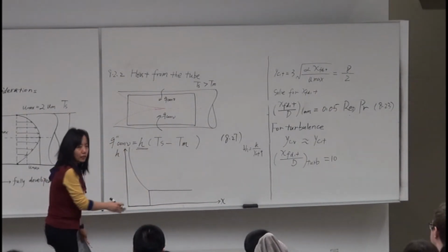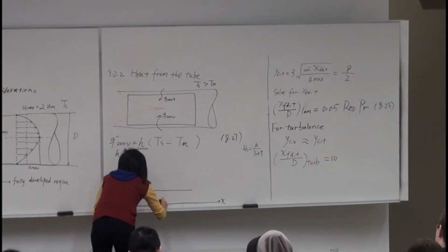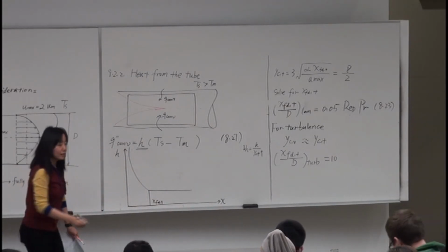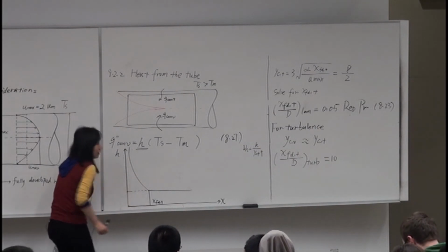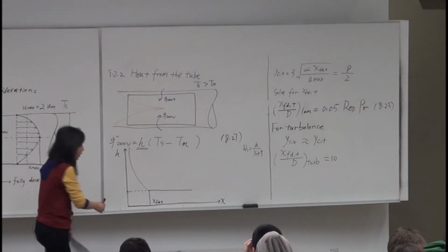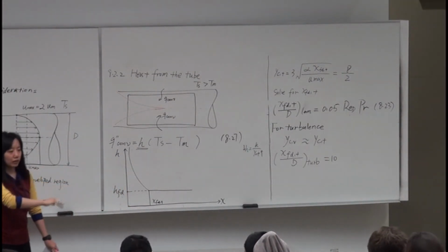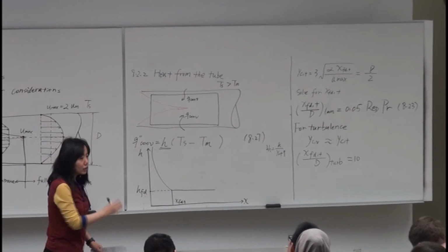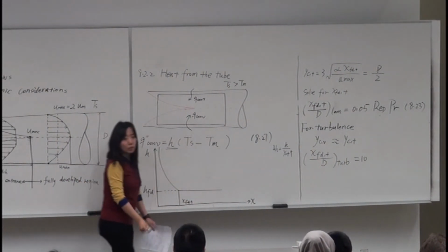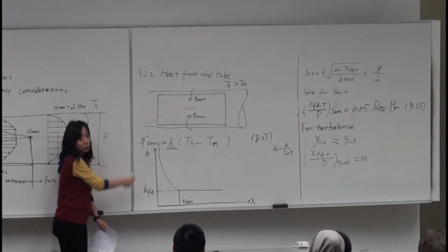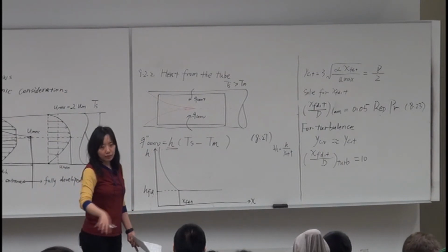The length of the tube where it remains constant is the fully developed thermal entry length, and now our convection heat transfer coefficient remains constant along the rest of the tube. That's the main difference. For external flow, it keeps approaching zero, but for internal flow, no. The thermal boundary layer merges at the entry length, then stays constant.